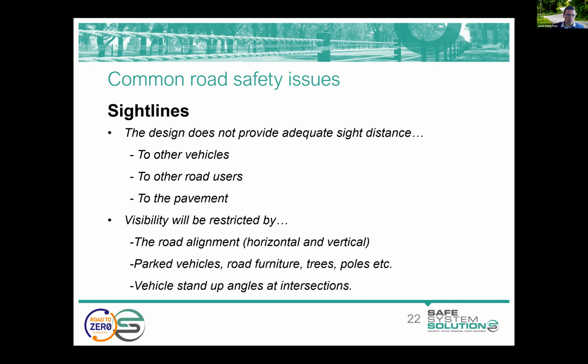And on top of that, we know that run-off road crash likelihood is increased at horizontal and vertical curves. So that's something that we try and avoid where possible, or if we are combining these elements, that we adopt geometry that's as generous as possible.